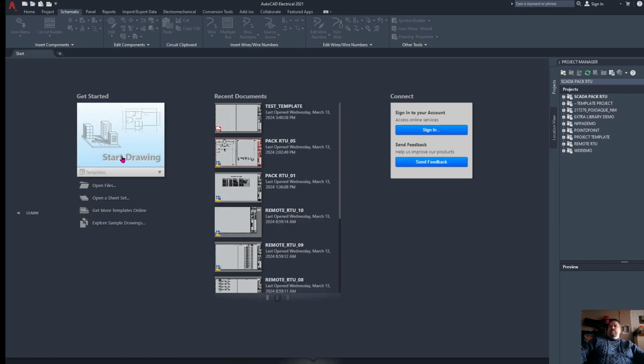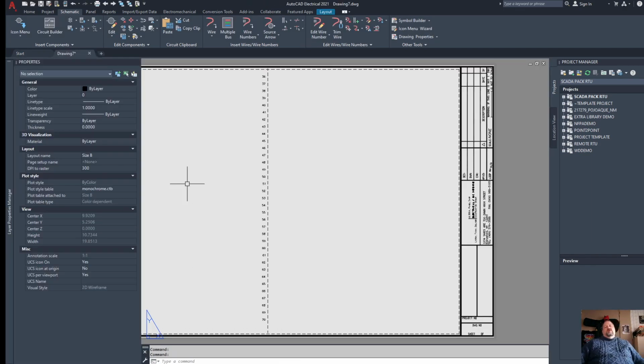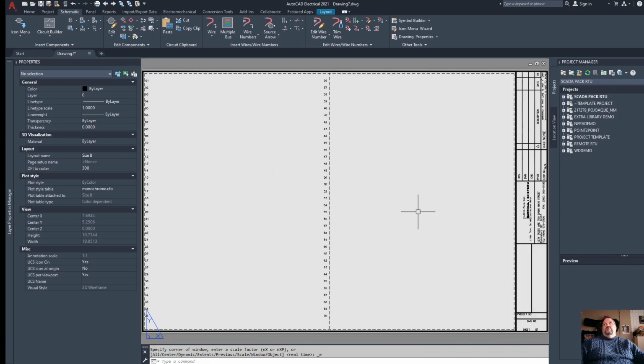and then this is AutoCAD 2021, and here you can click on this drawing. This will open whatever template you have designated as your QNew drawing, which now it opens up and it's there for you to use. So if you also click the new button up in the top left corner, if you hit new, you'll see it says down below it, it's QNew.